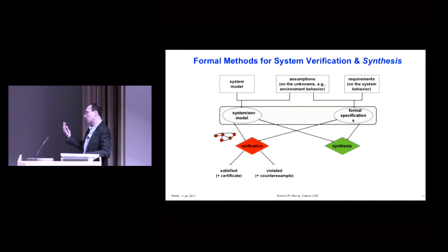And if you're a controls person, this is like LQR, right? I give you x dot equals ax plus bu, the system description. I give you the quadratic cost that I want to minimize. And I say, synthesize for me the controller that stabilizes the system and minimizes this cost, right? This is the same thing. Here's the system spec, here's the specification, synthesize the logic that does that.